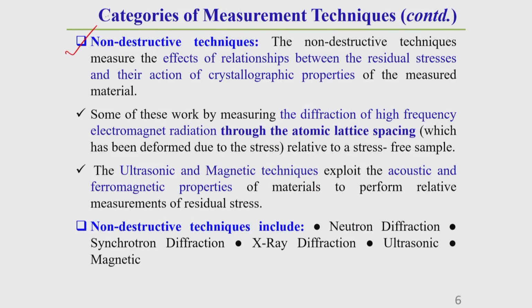Okay. These are very commonly used to measure the strain. So, once we measure the strain by using this strain rosette, we can easily measure the principal strain. How it is, I will show you in a subsequent slide. So, another technique is called the non-destructive residual stress measurement technique. In this technique, generally we measure the relationship between the residual stress and the crystallographic property of the material. This you should keep it in mind.